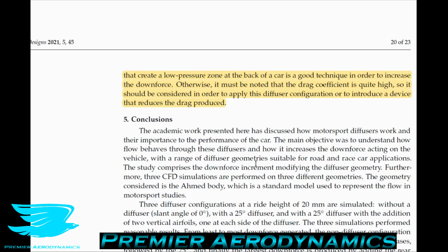Another way is to turbulate the flow. There are a few different ways, actually, I should say. First of all, with the current diffuser geometries, where you have a very sharp inlet angle, and that edge there is sharp, you can turbulate the flow to help it have enough energy to go around that corner. Another way is to round that corner so that the flow can go around and not separate. That way you can have a more efficient diffuser happening.